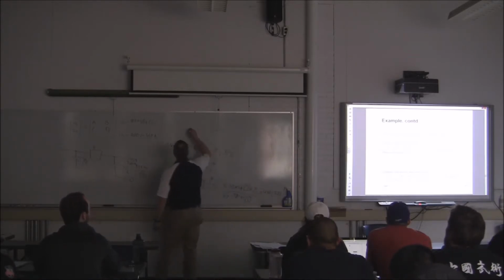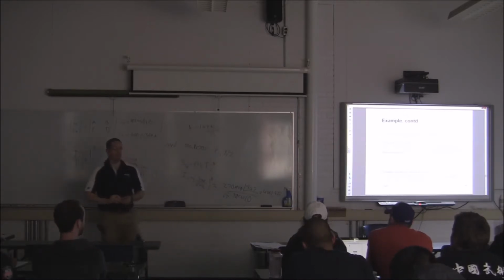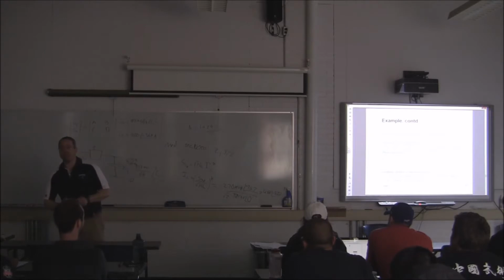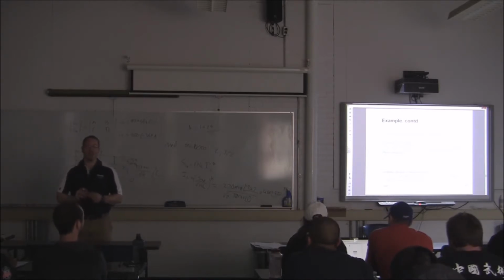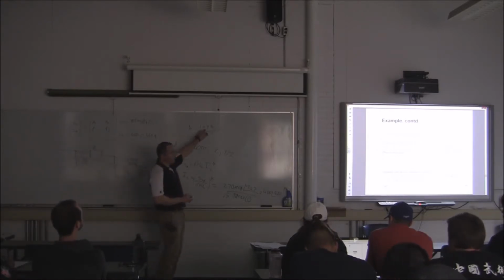A, we said, was 1 plus yz over 2. Notice, I no longer have y prime and z prime, right? Because in a medium length line, the hyperbolic sines and tangent disappear. It's 1 at an angle of 0. So I need to solve for y and z, and I'm good to go.